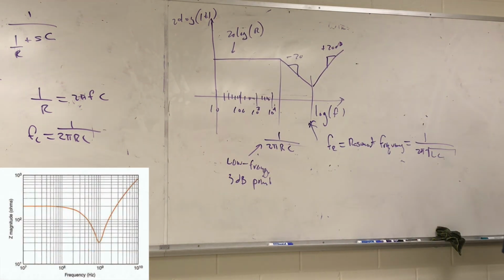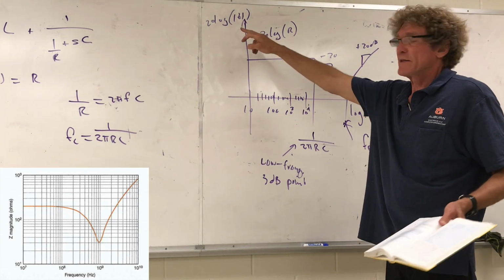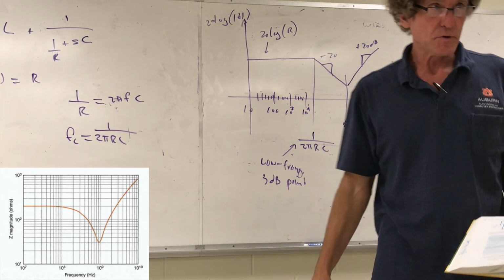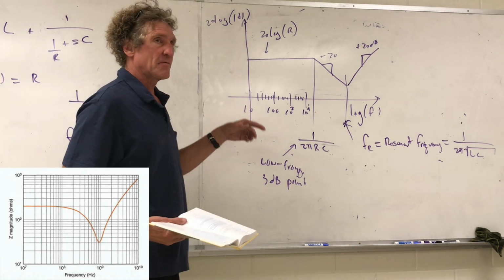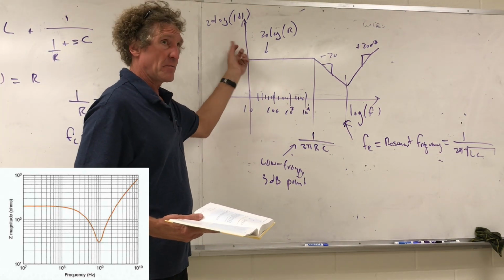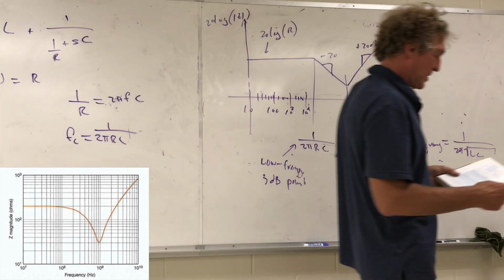This is shown. It's not a Bode. What he does is show you this. I wish he would have put a Bode. He shows you the actual values. Now remember, you don't have to put the 20 there, but typically they'll put 20 times the log of that. That way it's a true Bode. This is not a Bode, that's from measurements. Typically, in the stuff I'll give you, I will show you a Bode because that's almost always used. And if they say it's 20 times the log of R, then this will be in dB. Y'all follow me? If it's not, then you're going to get these gyrations and it'll say ohms. Either way, that's the plot.